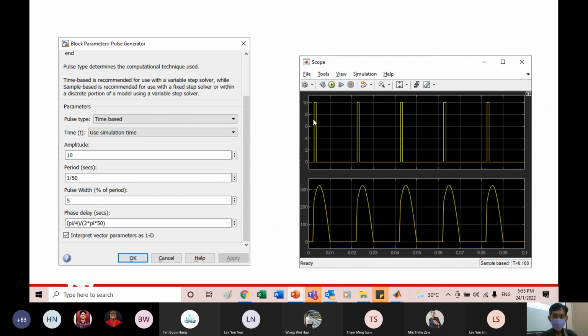After we do this, it will give you the idea of the conditions. You assume that all these pulses are just like a chopping knife, right? You move the chopping knife in the angle and you chop it off. At 90 degrees, you chop it in half. And the more you move, you eventually turn off the thyristor by changing the phase delay.